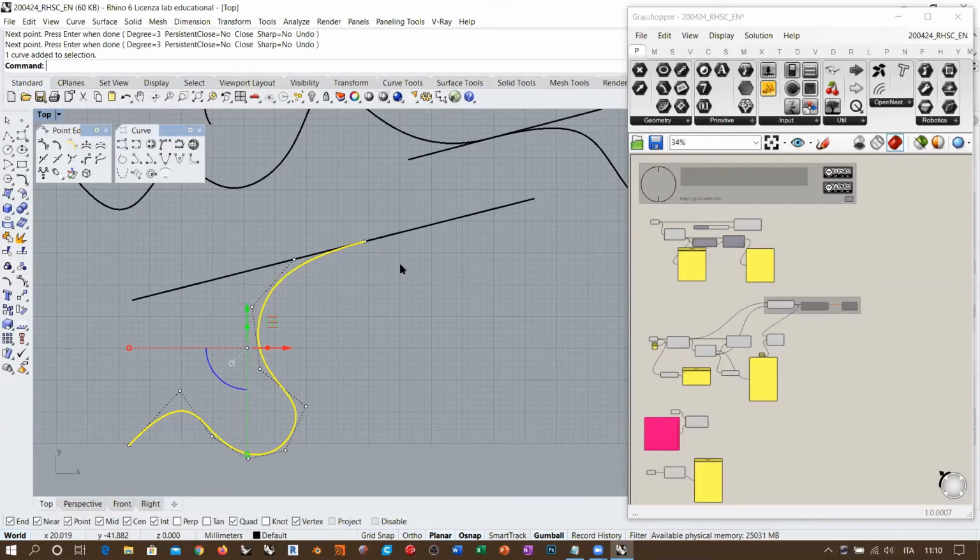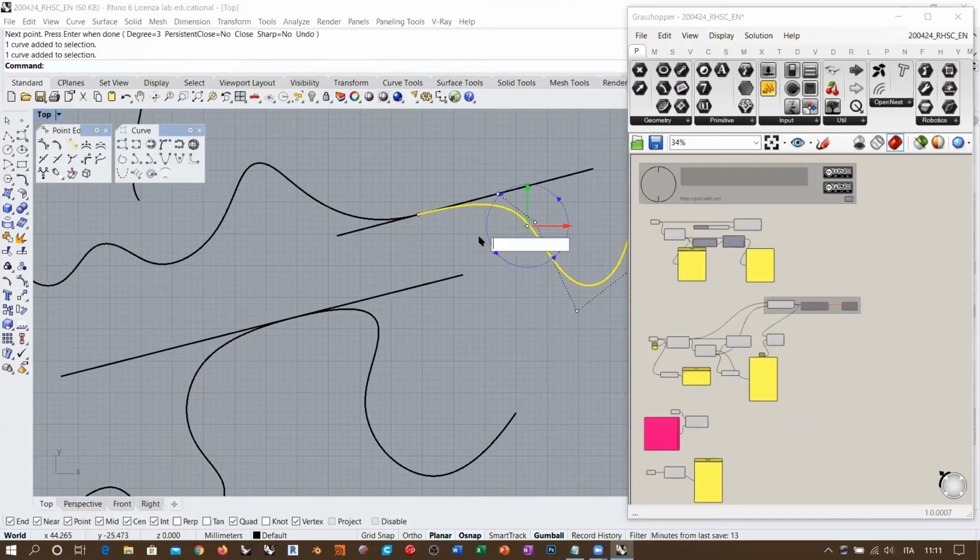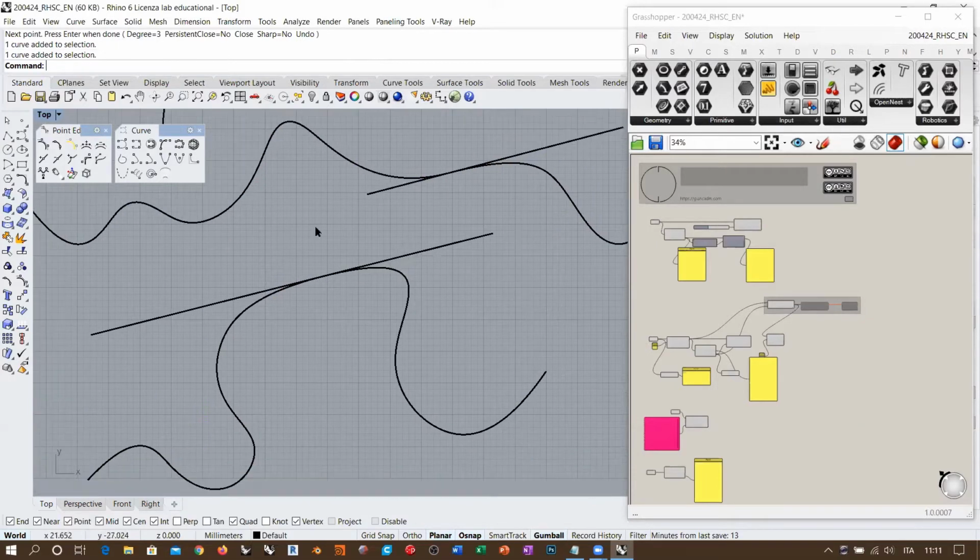Now, what if I start a new control point curve, starting from this point, and I want it to be tangent to the same line? That means I have to place a second control point along this line, and then I can move away and do whatever I want. Now, if we consider this as we did here in this scheme, we are reproducing exactly the same situation.